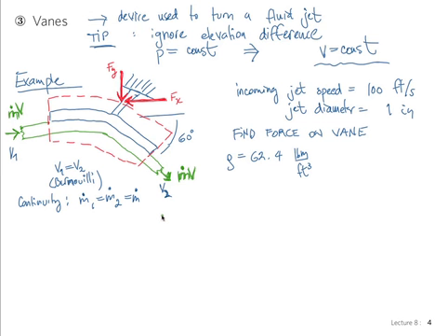Okay? So far so good, everyone? Any other questions? Now we're in pretty good shape. We've selected the control volume, we've drawn the forces on the control volume, and we've drawn our momentum fluxes. Now we're ready to use this. We write our momentum equation. The only difference with the previous examples is that now we have to actually write the momentum equation in vector form. We have two components, vertical and horizontal contributions, so we write the two components.